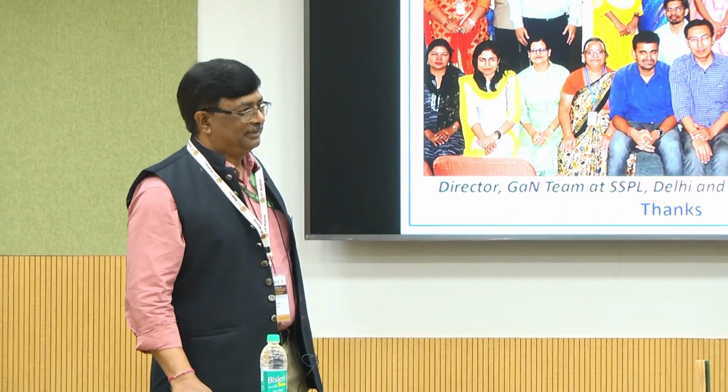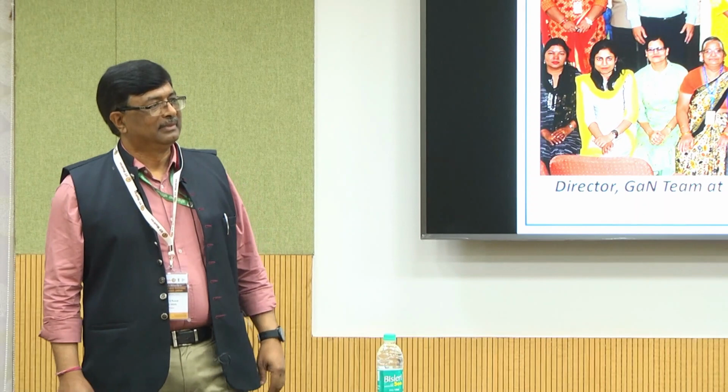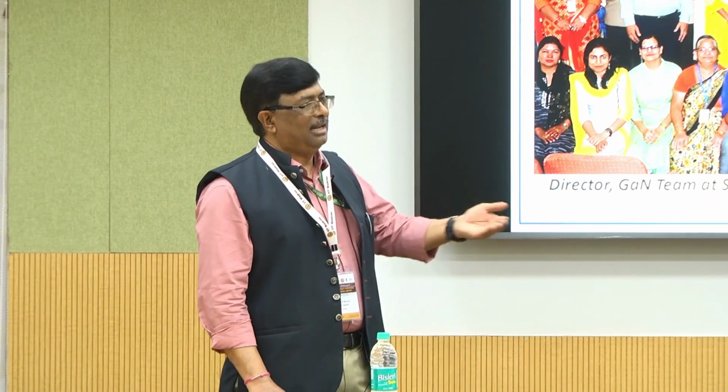We have made both kinds of devices. Indigenous devices are carbon doped, and to qualify our process, we use imported wafers also. They are iron doped. So the CV measurement? CV measurement was on carbon doped. So you haven't tested the buffer free? Buffer free not yet. We are just in the process of developing that. Because GaN is a well established company which is proposing this structure with buffer free. They are claiming that it is even better than the buffered one. So, that is how we are also going in that direction.